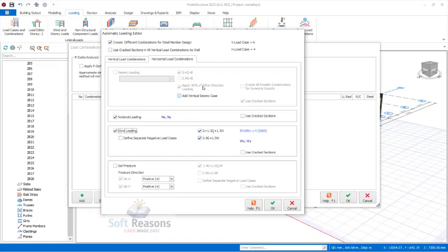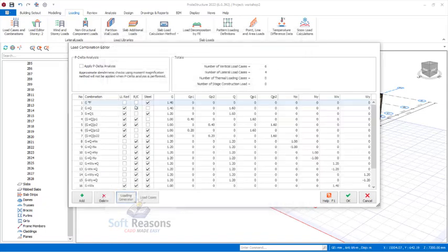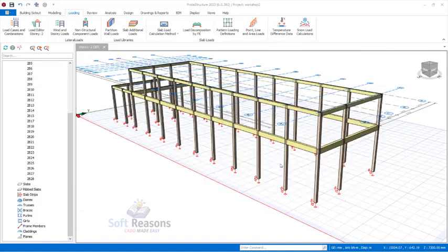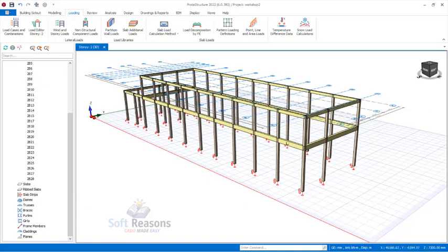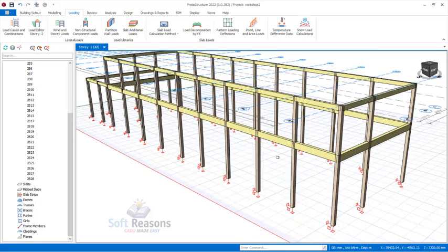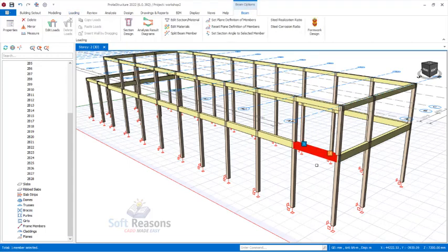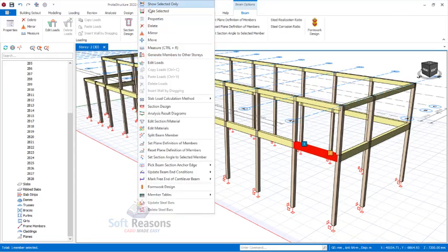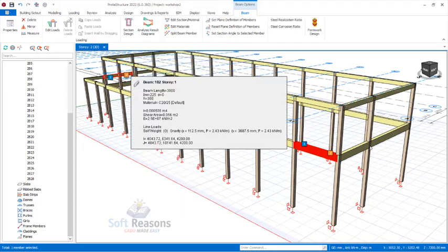We'll feed that in, and I will take us to where we feed that in. Click on the OK option. So we have the loading combination generated successfully, after which we click on OK and proceed to the load editor. For the load editor, you can select one of these B members, then right click, and in this drop down menu you can see edit loads. Or you can use these options right here. So click edit load, and let's edit the wall load that will be on these particular B members.